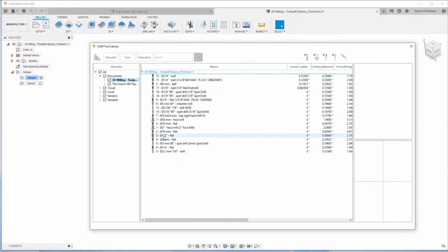Notice in here we have some tools, like I have two tool number ones, right? So they can't both occupy the same pocket in the machine, in this case for this job. Right, so I have two tool number fives, right? So I have a tool up here, a 6 millimeter ball. Down here I have a tool number 5, right? So if I click, I can filter, or not filter, but I can see them according to those different tools. Now, in some cases, it makes sense. I'm just going to renumber these, right?